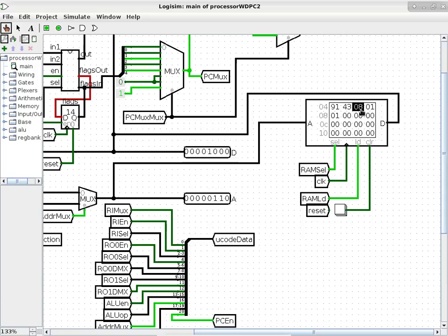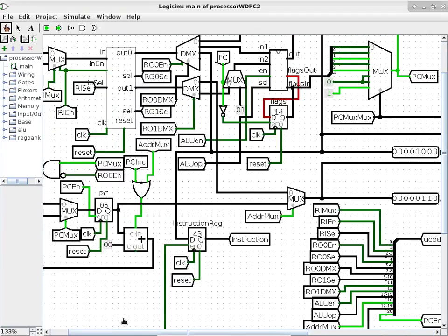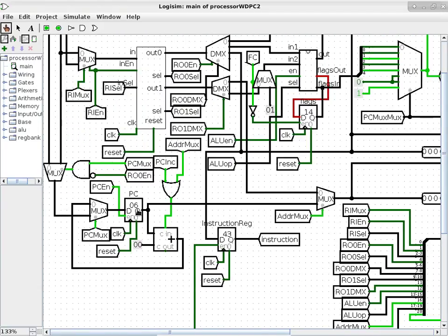Okay, so it doesn't hurt to single step a few more times just to double check. We want to look at the program counter to update from 06 to 08. So Control T, and you can see how it's updated to 08. So that means the halt instruction we're going to be stuck at is the one that is at location 8. And you can see how now the PC is 09. It is not going to move anymore because we are already at a halt instruction. So we fixed the problem by analyzing, okay, this is not supposed to happen, and we go back to the ROM, locate the correct bit to change, in this case fix it, verify the change, and make sure that it's all working now.